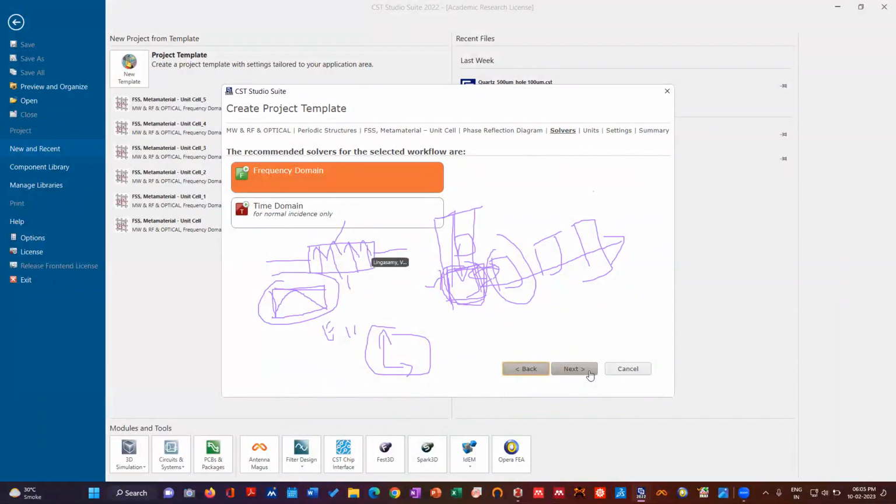This is like a front view. If you look at the waveguide like this, you can see here you will have the unit cell basically. Here the plane waves are there. It is a TEM waveguide where you will define this as an electric plane, tangential E equal to 0. This you model as tangential H equal to 0, or we can say magnetic wall. This is electric wall. So your plane wave is just incident on that and comes back.